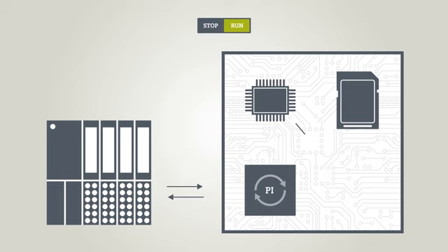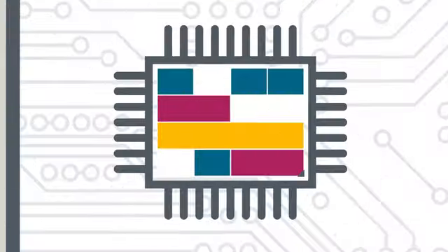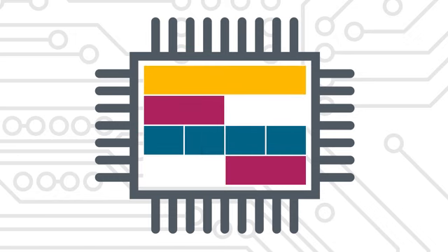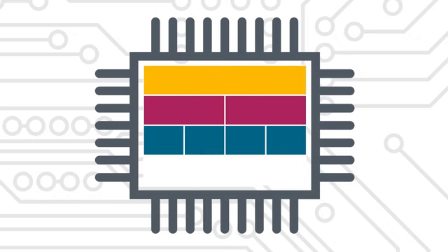Important data is written to the embedded retentive memory when the controller is set to STOP and will be available again at the next startup. You define during programming which data is to be handled as retentive. The SIMATIC S7-1200 and S7-1500 controllers have an optimized data filing system. This system significantly reduces memory requirements and access times.